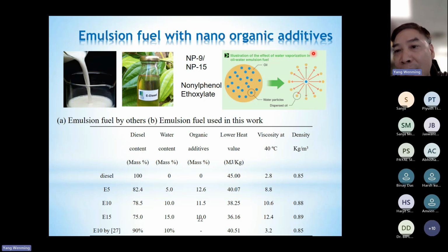Okay, so this is an explosion. We call it the macro explosion. This macro explosion can improve the fuel mixing process and increase the surface area, thereby also improving the fuel evaporation speed. So it can produce a faster expansion speed, or evaporation speed, correct? Thereby can improve the combustion process.